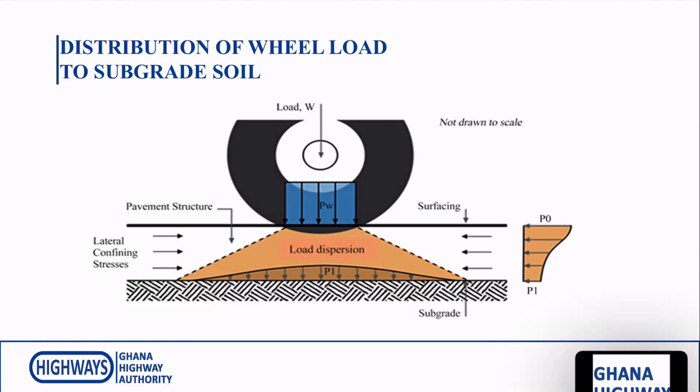To perform this function, bases and subbases must be built with adequate internal strength. Furthermore, they must retain these properties throughout the life of the pavement. Hence, it is important to consider routine maintenance and good drainage.